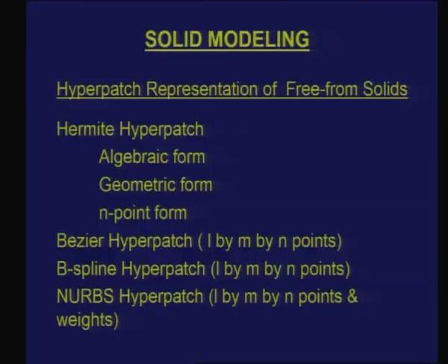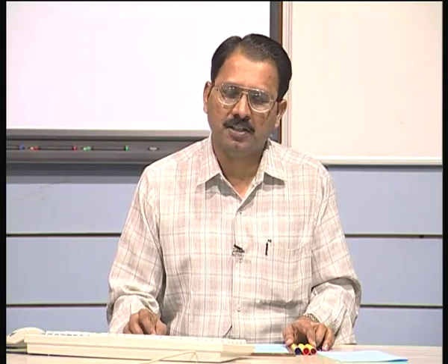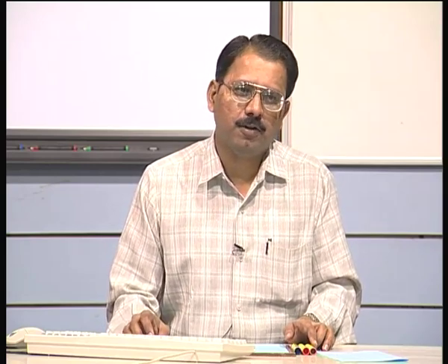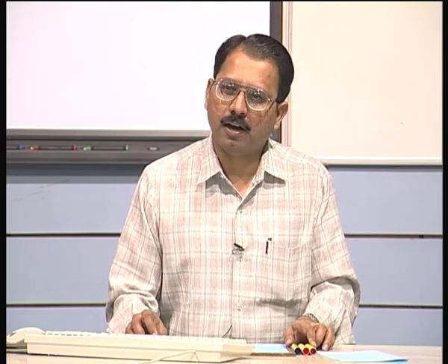This is not a very convenient way to model solids, because most of the solids which we come across, particularly in engineering applications, are not free-form solids, and so it is not a very convenient way to model them. Suppose I want to model a simple cube, a NURBS hyperpatch representation would be a very difficult way of looking at a very simple solid. But it has its own applications, particularly in computer graphics and others.